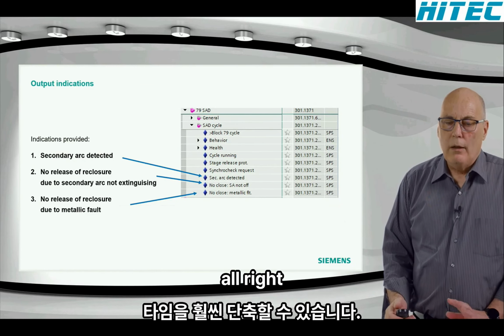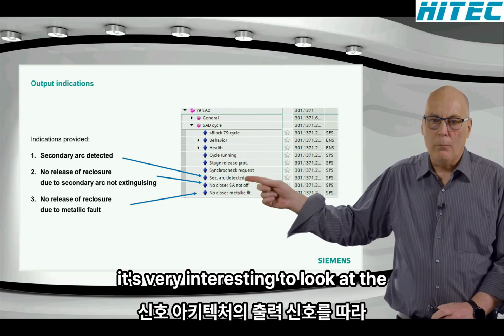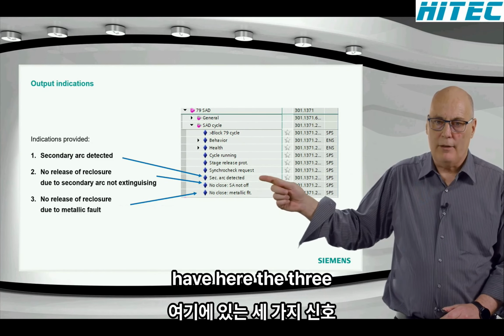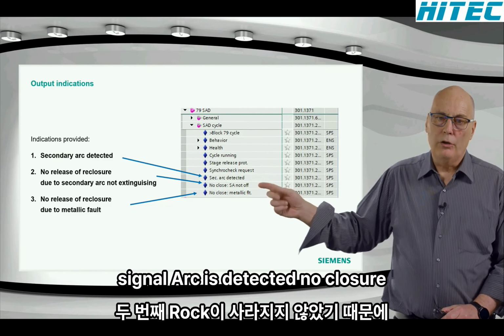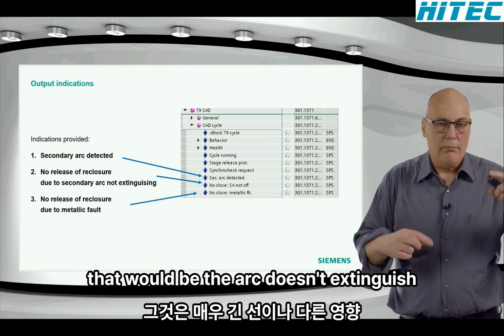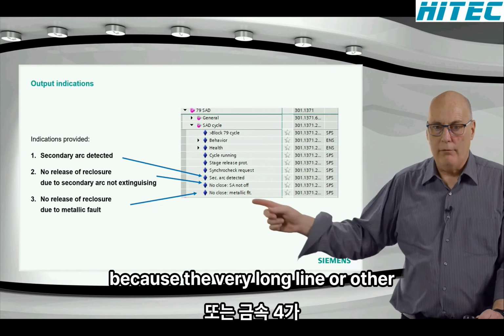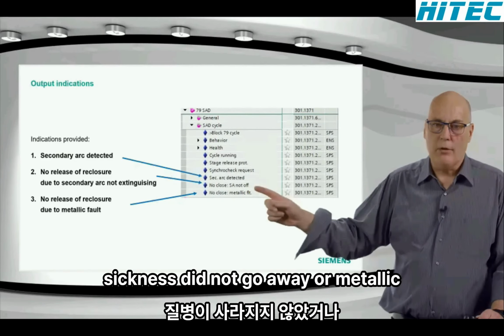All right. Alarms, if you're going to apply this, then it's very interesting to look at the output signal. I call them alarm, the output signaling of the secondary arc detection. You have here the three. Secondary arc is detected. No closure because the secondary arc did not go away. That would be the arc doesn't extinguish because of the very long line or other influences, or metallic fault. These are the reasons for no closure. Either secondary arc did not go away or metallic fault.